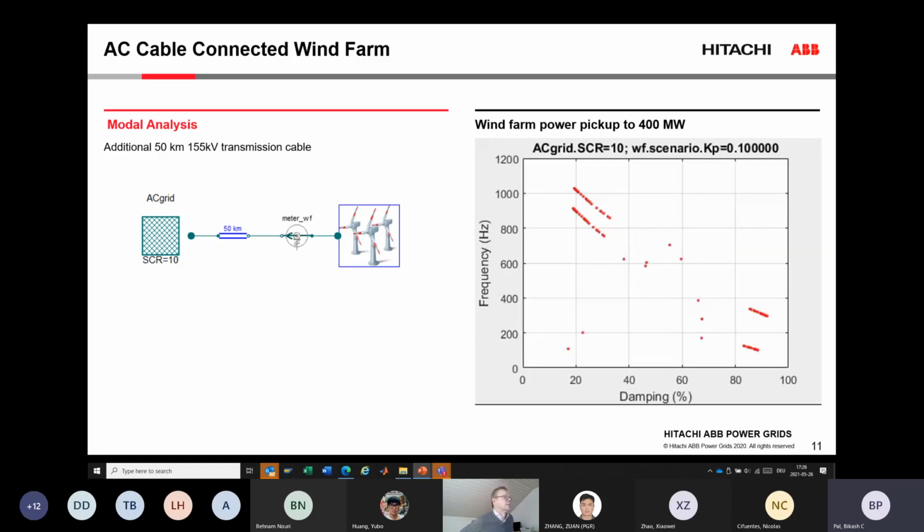So it was the control loop within the wind farm. Yeah, that was the problem. But the grid changed, of course, its strength. But that control loop, they had some setting issues. So maybe in a digital control, rather than a -1, they put a +1. So that type of thing happened. Anyway, so.